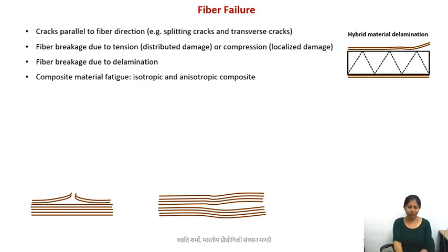Composite material fatigue. Composite materials also experience fatigue, but the mechanism of studying these fatigues is quite different compared to that of metals. Metals are isotropic materials. What do we mean by isotropic material? The material has the same properties in all directions, but this is not the same with composite materials, especially the fiber-based